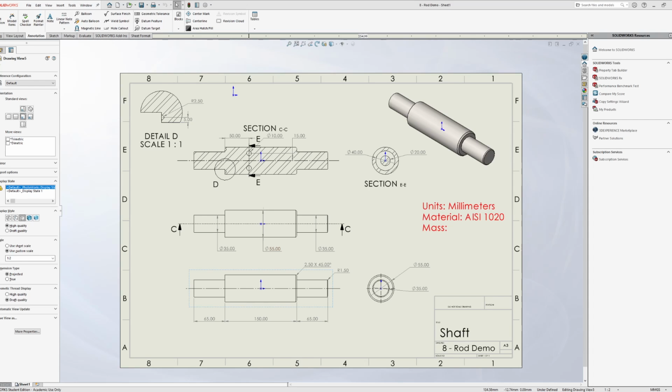I probably should have added another, yeah. When I was going through the PowerPoint, I likely should have added another cross-section view just to make that a little bit more apparent, but you're right, and I'm glad that you pointed that out. Since we are labeling something that, if you're looking directly at it, is just a rectangle, but it's giving you a cylindrical value, then that's implication enough that it's actually not just a square cutout, it's cylindrical.